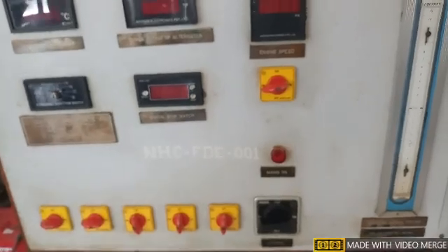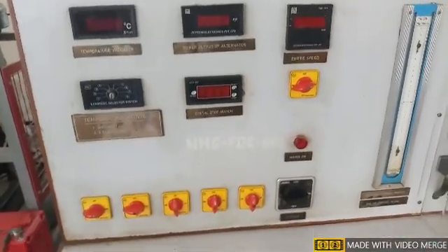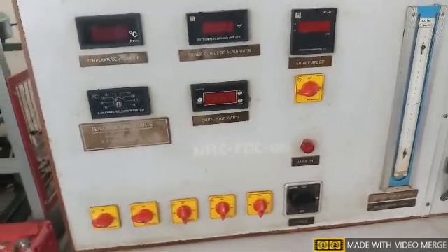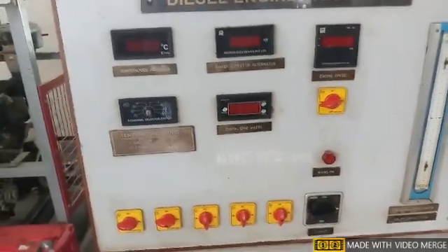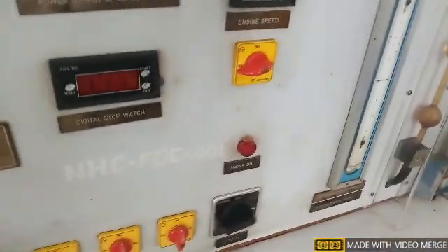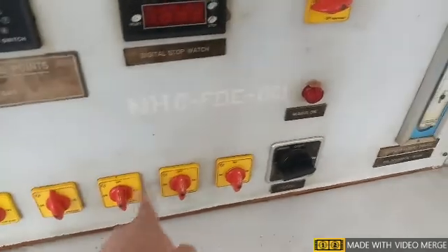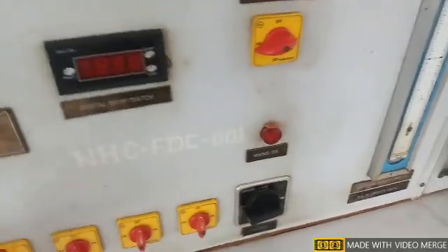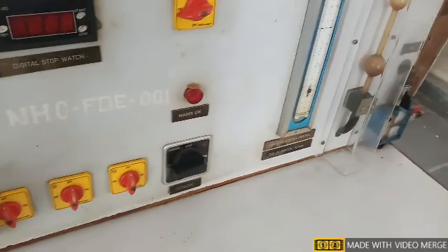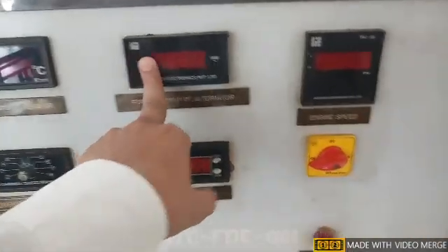We have different types of loading for engines, such as hydraulic loading, mechanical loading and electrical loading. What we are using here is electrical loading. So here it is 0.5 kilowatts, then 1.5 to 2.5 kilowatts. Once you increase the loads, you can see various fluctuations in the power output as well as the speed.